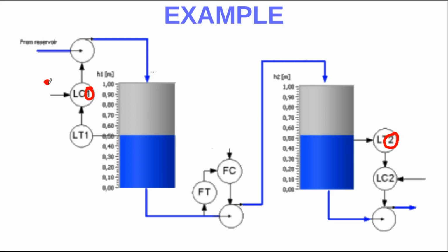As you can see here, we have the set point. This is the level we desire in this tank, but this is an electrical value. This is the process variable. This is the measured process variable, while this is the controller action, again to a pump that makes water come as an inflow to this tank.